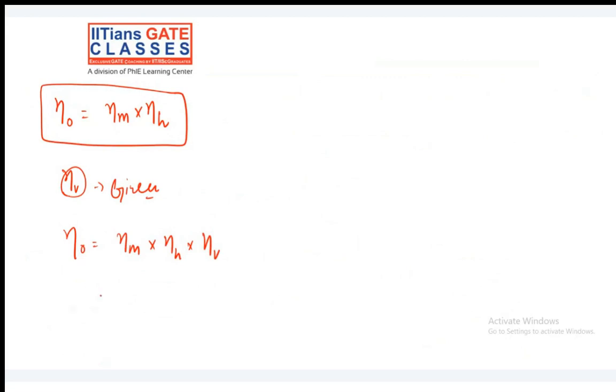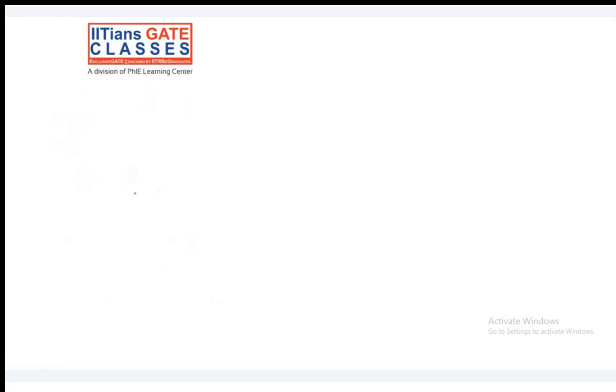So can I say that the first thing we have is water power, which is greater than whom? Runner power. And this runner power is greater than whom? Shaft power. And this shaft power is greater than whom? Generator power. Yes or no? This we are not worried about, meaning generator power, because my job is done at the shaft power. So water power is greater than runner power, greater than shaft power, and this is greater than generator power. Now, classification of hydraulic turbines, an important part, classification.